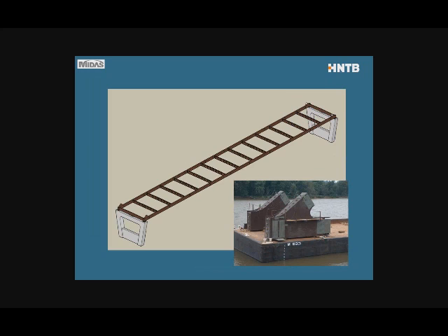In the next picture, I added the tie girders. Those are the longitudinal girders. Then we have the intermediate floor beams, and then in the corners are the knuckle joints. Those are very complicated elements. They're quite difficult to design too, because this is where the arch rib, the tie girder, and the end floor beam all come together. And you also have to design for bearing replacement.